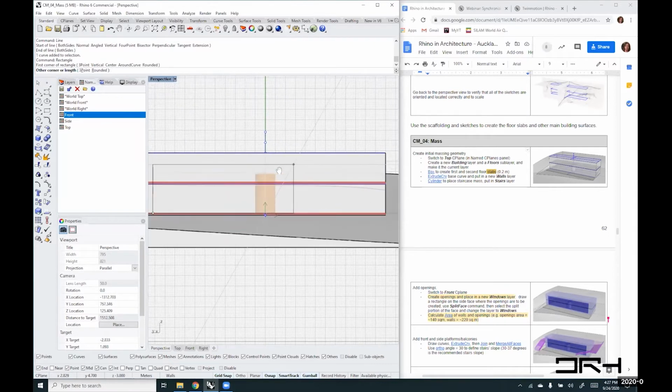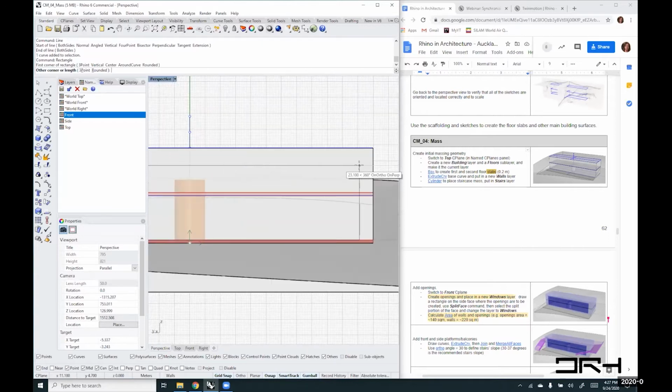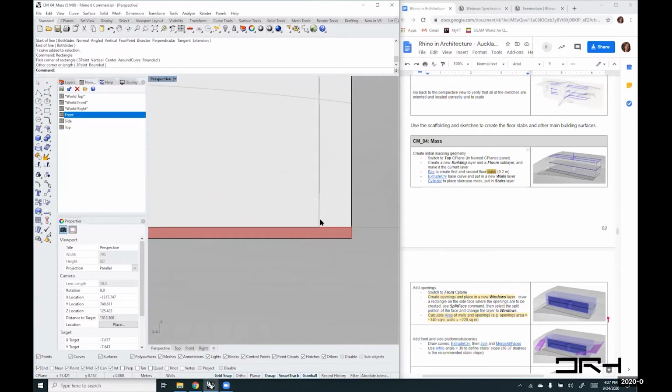And now at the other end, I also want 0.8 from the edge. And it's kind of hard here because I don't have anything to snap to give me that reference. So I'll just estimate here to go there and then actually measure the distance from here to here, and it's 0.6 meters, so that's really not exactly what I wanted.